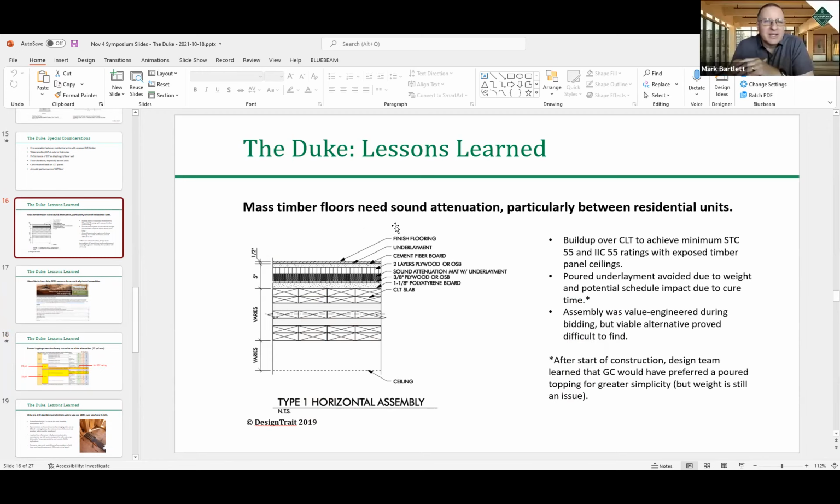Yep. One of the things I think is really important when you're considering a mass timber project is that there are a lot of decisions that need to be made very early in the project that affect a lot of different things. You think about acoustics, that might be something you can put off until later. But it's a huge impact on the CLT slab, depending on the thickness of the CLT, or I'm going to say mass timber because it could be DLT as well. But how much topping slab obviously affects the overall weight. It affects the acoustics. It affects how far the material can span.